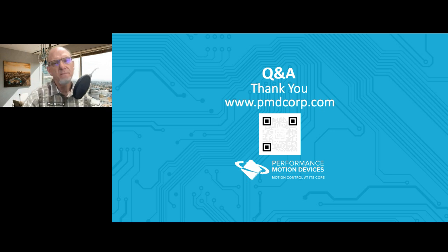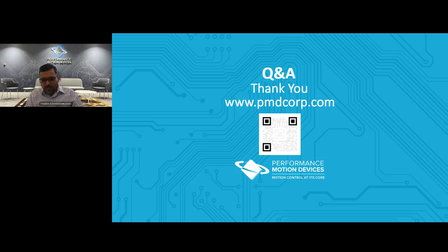Yeah, so in our chips and drives, we have a sync signal that you can tie between the drives together. What that does is it synchronizes the PWM loop. So within the chips, there's a PWM loop that's running, and all of them start the whole PWM interrupt cycle at the exact same point. So if you command a position on each of these chips, they move at the exact same time. So that's how they synchronize across. So we have pretty elaborate synchronization between the chips and drives.